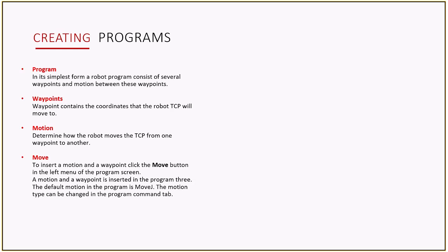Why is this important? Because if you are in a wider work area, it doesn't matter how you're getting towards the product, right? But if you have other robots and people walking around and it's a busier work area, you want the robot to move in a certain pattern and in a certain straight line, as straight as possible. So that's important when you're programming the robot.